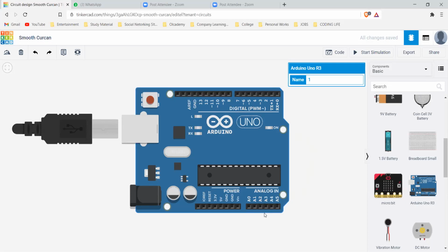So if you consider that we are reading temperature right now, okay? Reading temperature cannot be 0 or 1. It has some kind of a value. Or if you're measuring a distance, distance can be in centimeters, meters, inches. It cannot be 0 or 1. So these values are read with analog, and if you just have to check if there is something in front or there is not, like you are just checking if there is something, that means it can either be 1 or 0. There is something present or there is not something present.